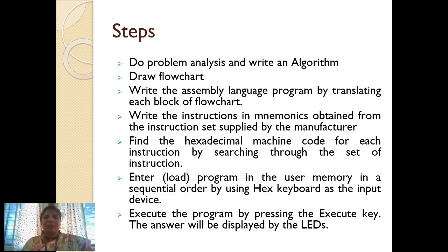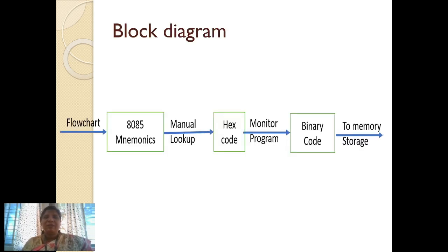Next, enter the program in the user memory in sequential order using the hex keyboard, and then execute the program by pressing the execute key. At the end, the answer will be displayed by the LEDs. All these steps we will see in detail by considering one example.